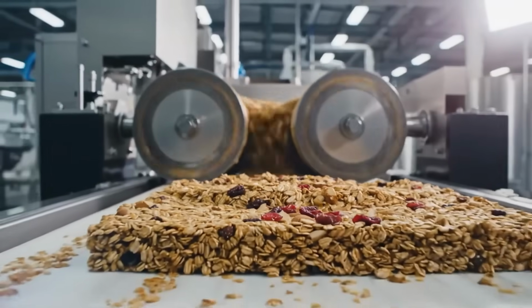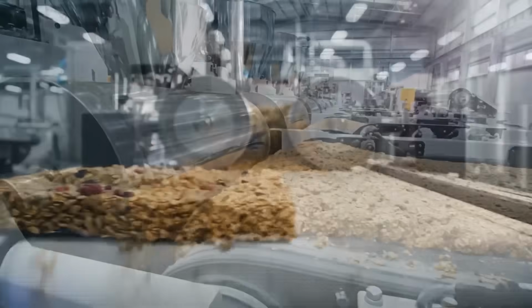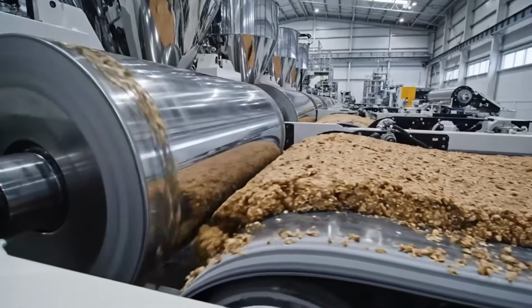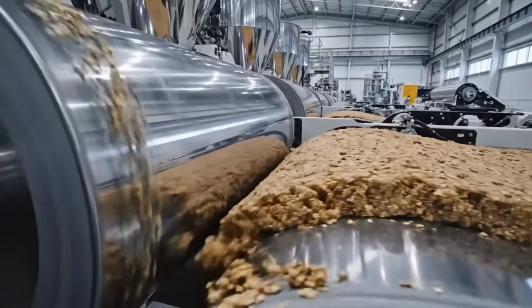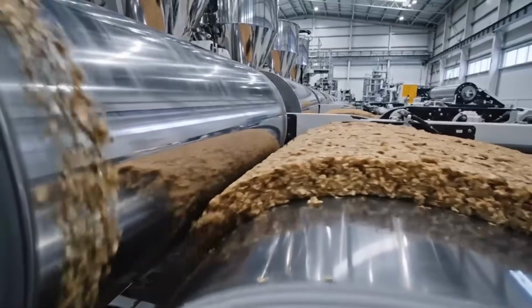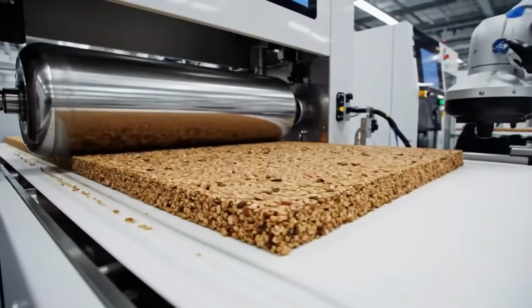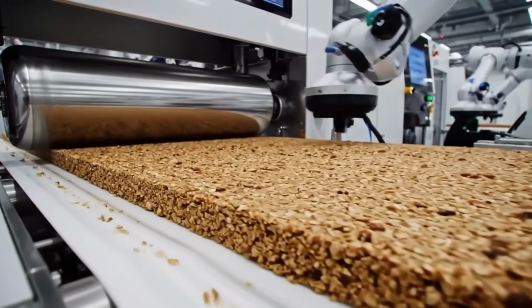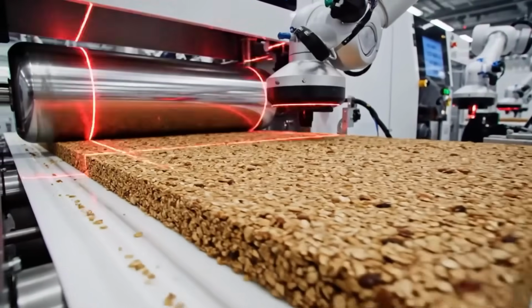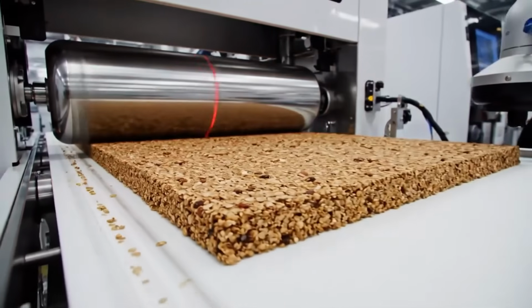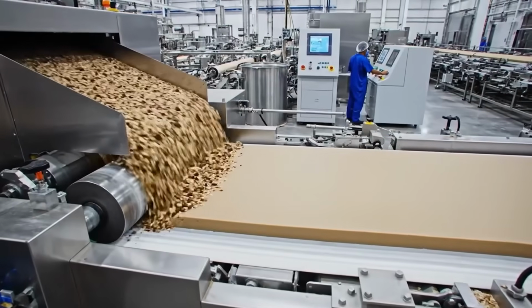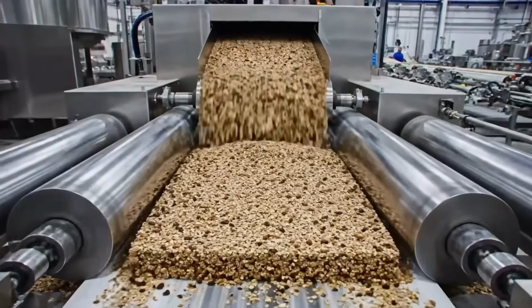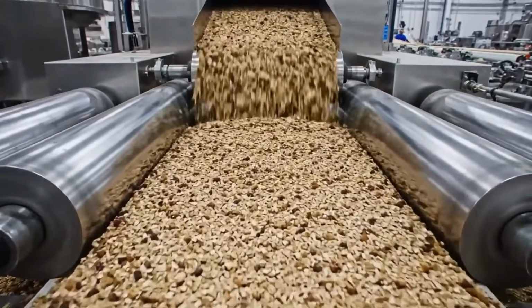For no-bake oat bars, setting is achieved by cooling rather than baking. The slab enters a cooling tunnel where fats crystallize and binders firm. Cooling profile is staged to prevent cracking. Rapid surface cooling can create a hard skin while the core remains soft. A staged profile cools evenly and yields a uniform firmness for cutting.